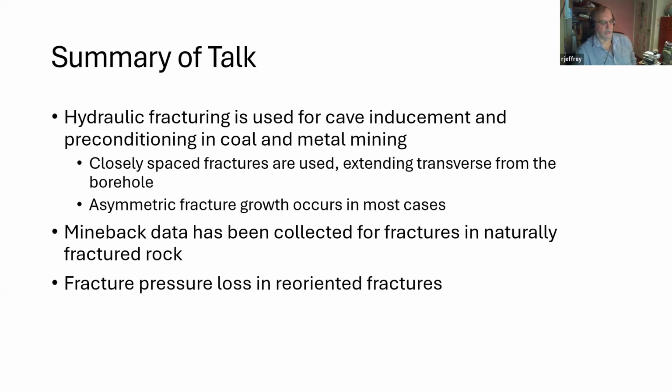And I'll point out how some of the aspects of fracture growth that we observed while doing that preconditioning are related to what's seen in both shale gas and geothermal fracturing, where we have closely spaced fractures that are extended transversely from the borehole or well. And we see quite often, for example, also asymmetric fracture growth with respect to the well.